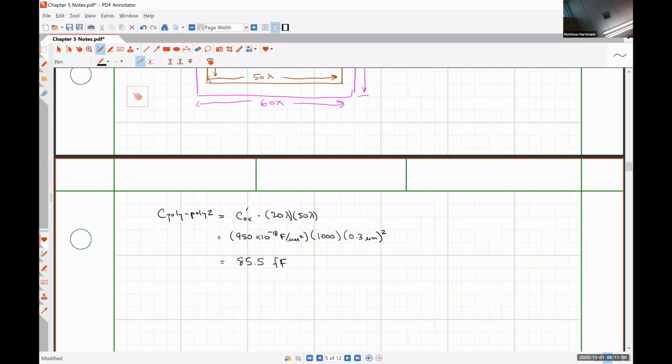Now we also need to know the capacitance of the poly layer, or the area capacitance of the poly layer with respect to the substrate, so give me just a second to find that value for you. I think I have it as 86 attofarads per micron squared, but I want to show you where I'm getting that, and make sure.